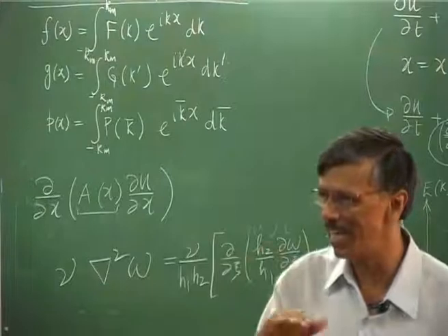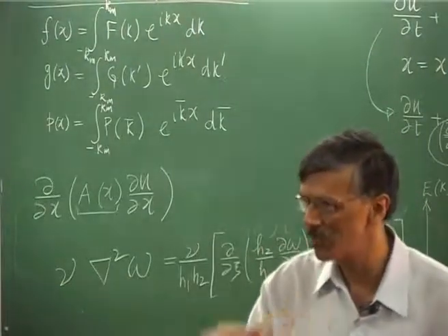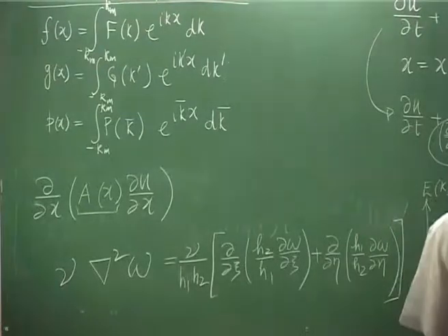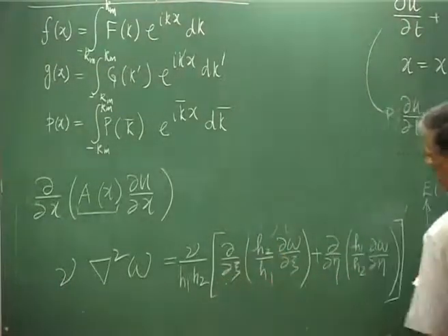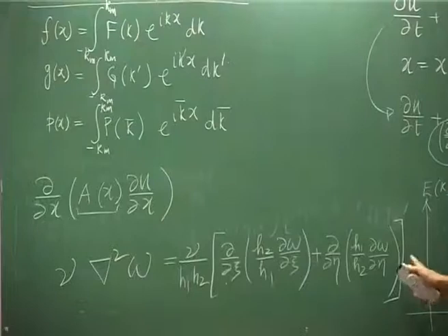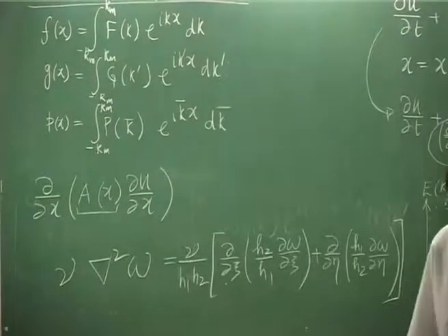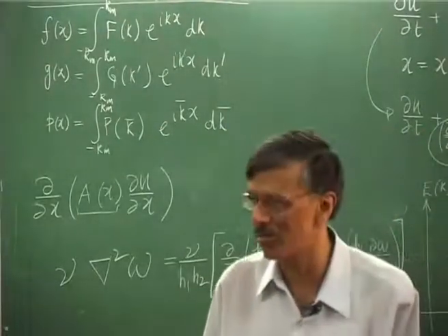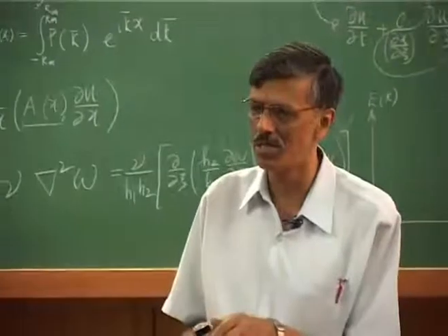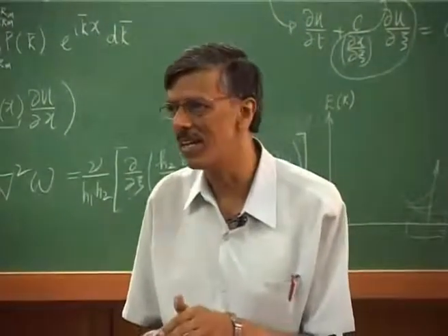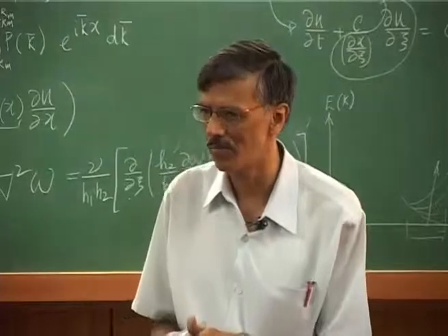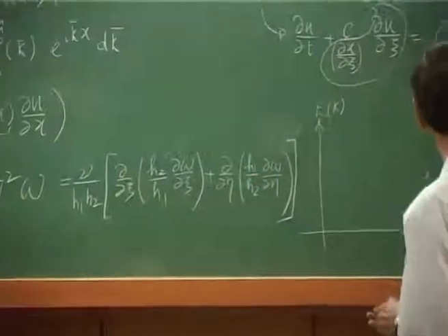If I am integrating, it has an effect of smoothing out. So we have a term, and I am furthermore differentiating, and it can be a serious source of aliasing. So please do not be swayed by any such statements where people say aliasing is a nonlinear instability problem. Aliasing is equally bad for linear problems, right? So let's keep that in mind.